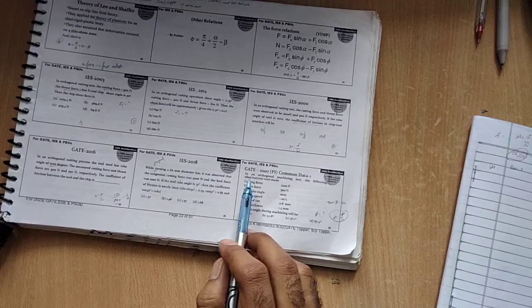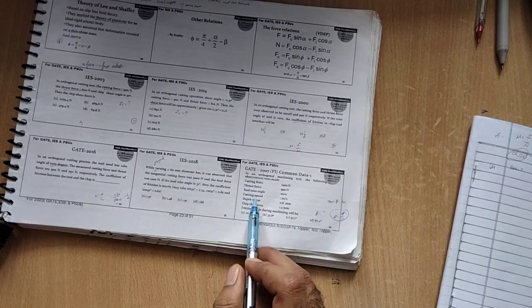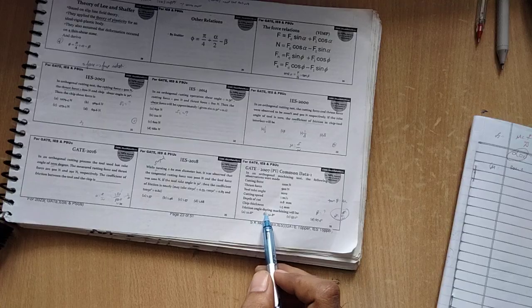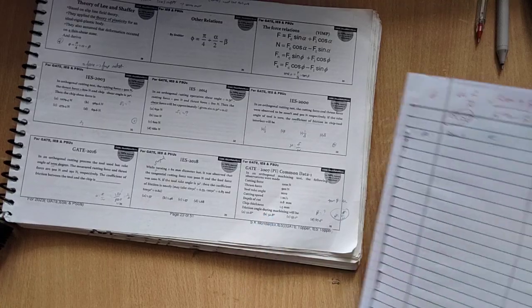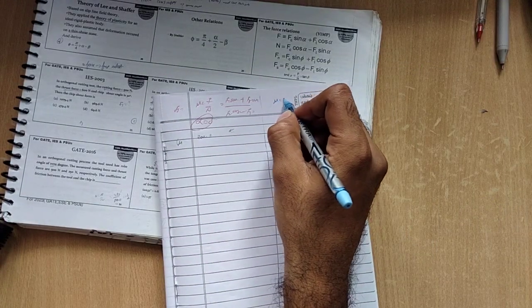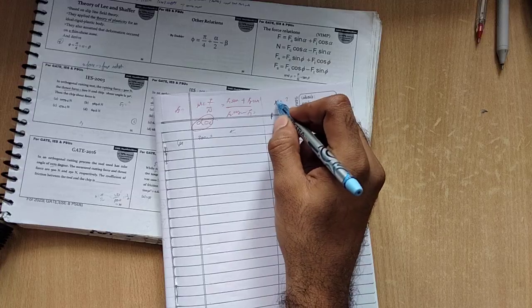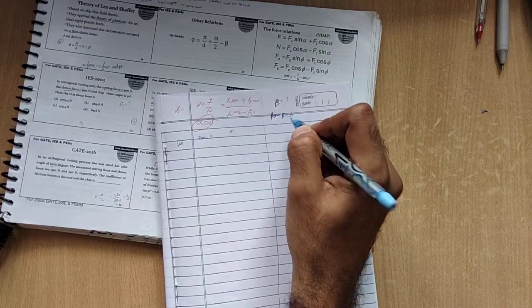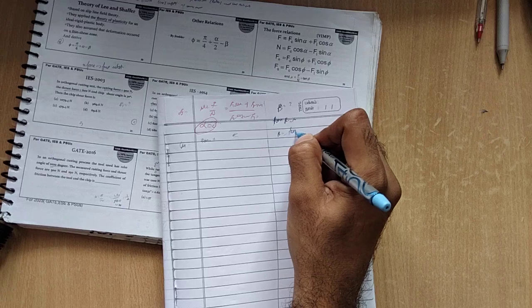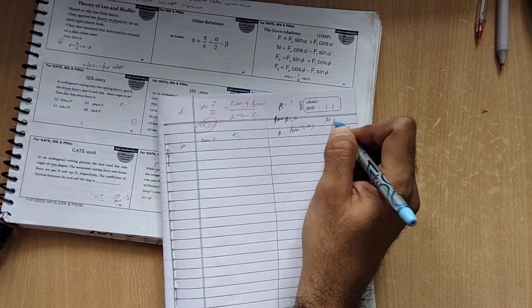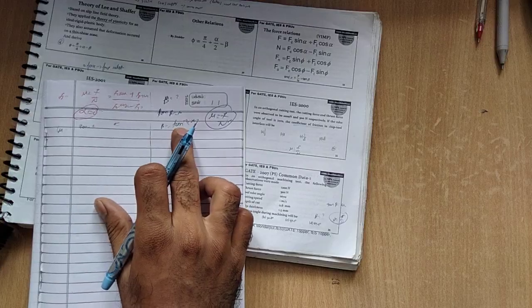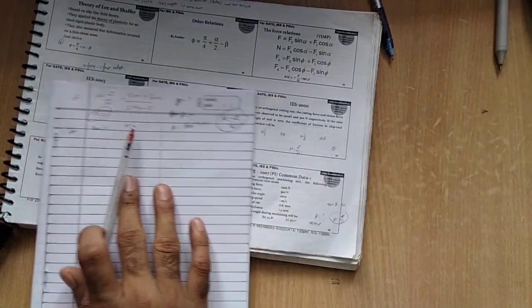So next one, in orthogonal cutting, the cutting force and feed force are given, along with tool direction, cutting speed, depth of cut, and chip thickness. They are asking for the friction angle between the tool and chip. Let it be beta, so tan beta equals nu, so beta equals tan inverse of nu. Nu is F divided by N. Calculate F divided by N, put it here, and take the tan inverse, and you will get the answer. That's it.